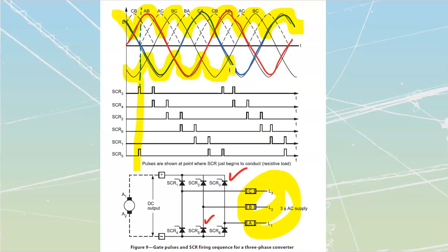And that is the line that we want to surf, because that is going to give us the maximum displacement. In other words, at all times, we want to be in between the top line and the bottom line. And we're going to have to change components in order to do so. So looking at this section that we have here, I'm just going to erase those over there. Looking at this section over here, we see that right now we want to be between the black phase, that's our B phase, and our red phase, right? This is the top line over here, this is the bottom line, so I want to be between my A phase and my B phase.